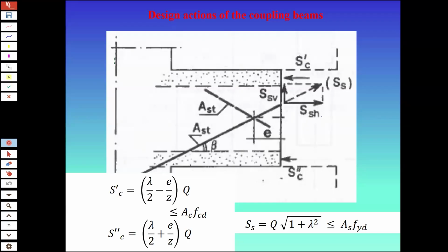Well, but here you will say, that is a bar embedded into concrete. Yeah, but here we are designing for ultimate limit state. We can imagine that concrete is cracked and in some way can even be spalled out. So the effectiveness in confining the bar is lost. But that is the reason for which we have to provide the steel hoops, because we have to confine.